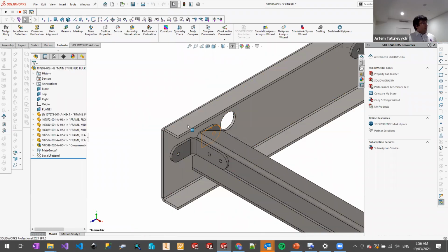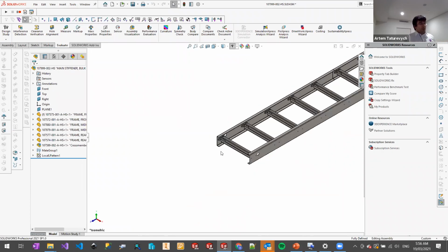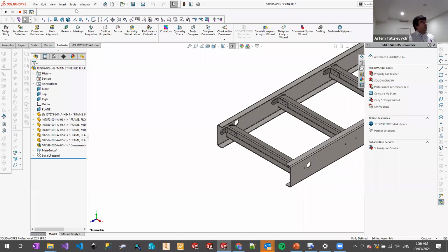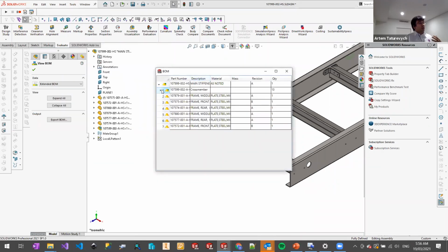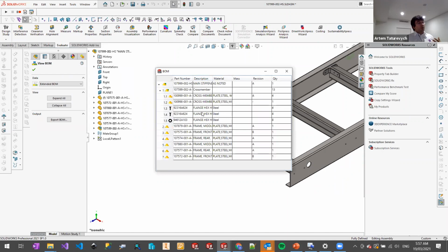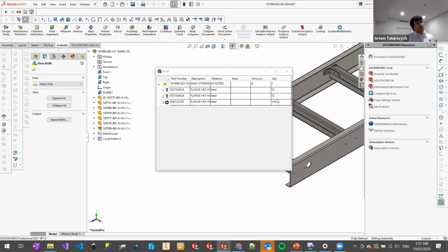Yeah, so look, if I go here, which is my top level assembly, of course I don't see the bolts here, but if I go to Tools, BOM Plus, Bill of Materials, View BOM, I'm going to see those items under the BOM itself. And I can select a different configuration here, different templates, for example to see items only. I want to point out that this screw is used 4 times, and the subassembly is used 13 times. So if I do items only, you can see that these quantities are multiplied. So this is your bolt list, which you can export.